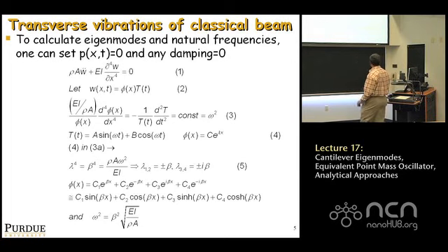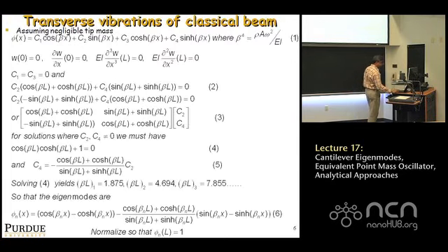How do we do that? This is where now we go into the boundary conditions, okay? And so we're going to do the simple boundary condition, which is to say that the tip mass is 0. So on the left-hand side, where the beam is clamped, the W(0) is 0, which means the deflection is 0. The slope is going to be 0 since it's flush, there's no bending slope.